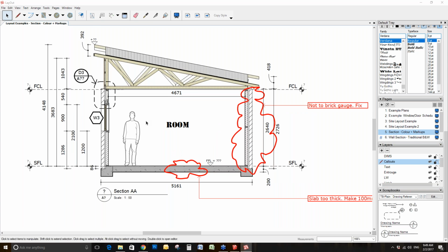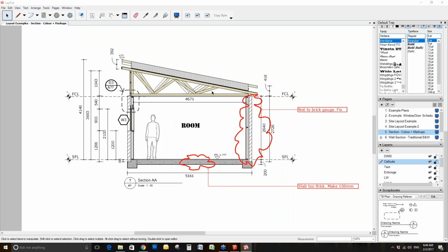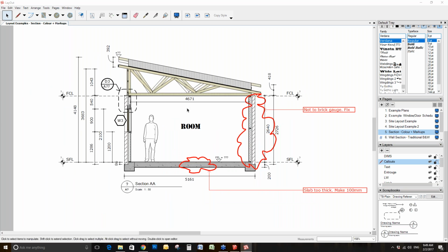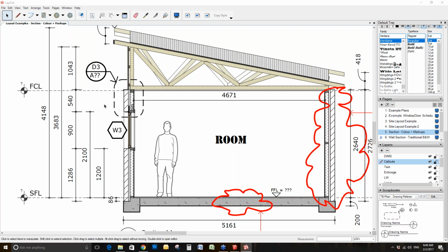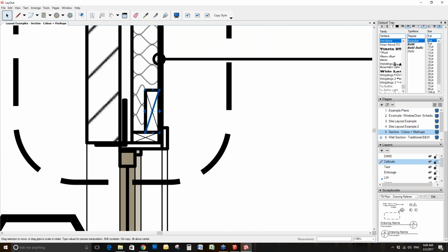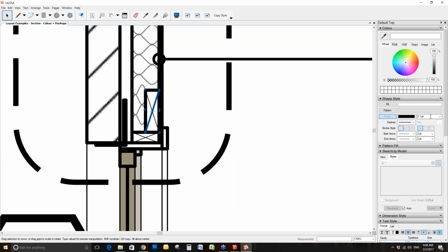So, quick example. Again, the most important thing here is that all of the work's been done for me inside of the section that I did inside of my Plusspec for SketchUp model. However, I have put in a little line work just to ensure that I'm capturing it and it's reading the way I want it to read. Setting the line weight by going into my line tool. In your stroke, you can set the stroke, the line weights, the line styles,